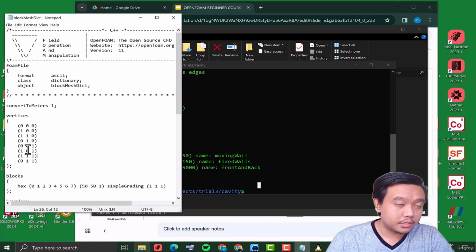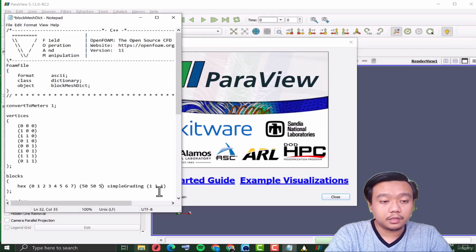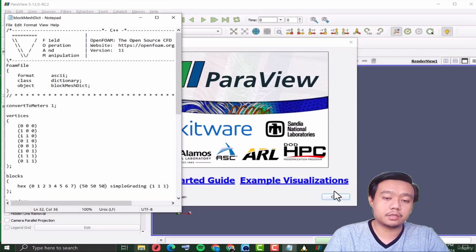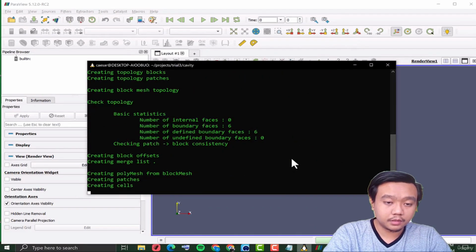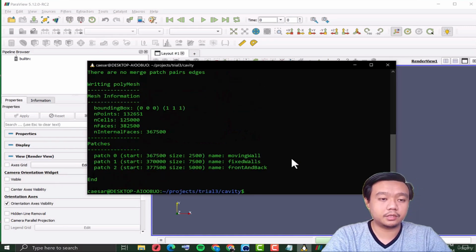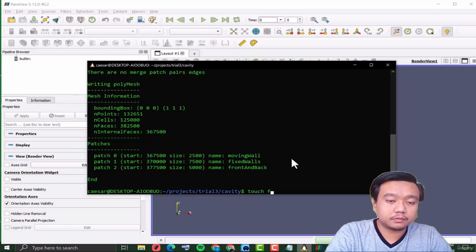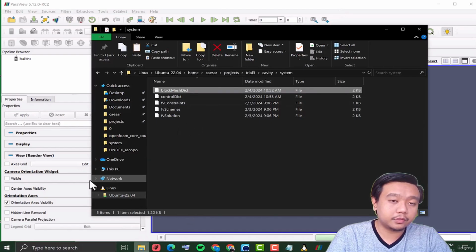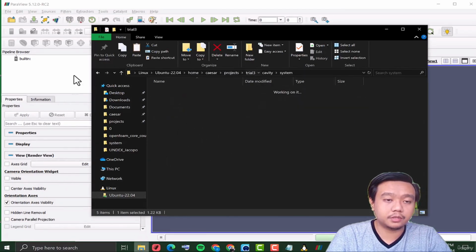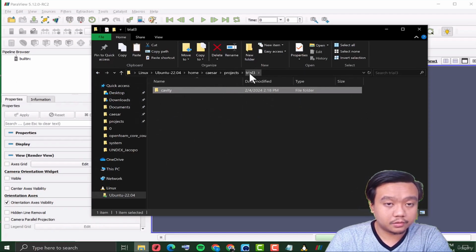If we change the mesh with the same size in every direction, I must also make it 50 in the z direction, so we can make the distribution of the resolution even and regular. So just touch foam.foam, and I prefer to drag and drop here, because it is easier if you want to just reload the file. So it's your preference.